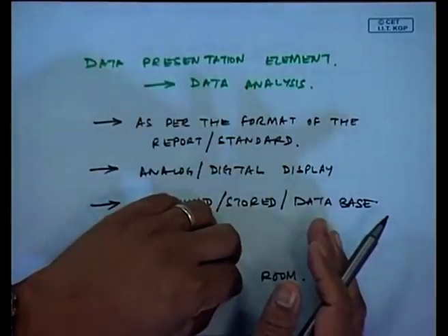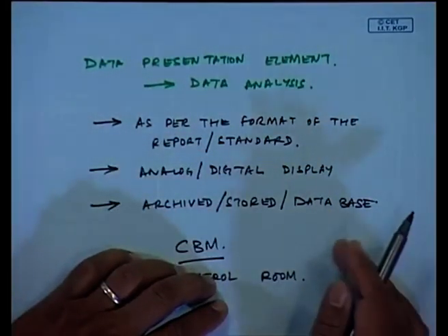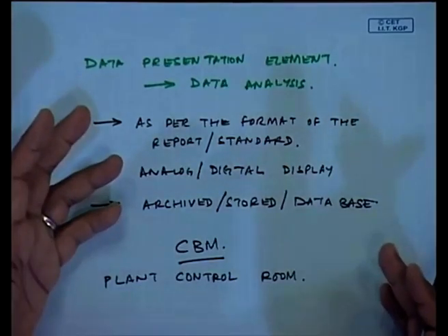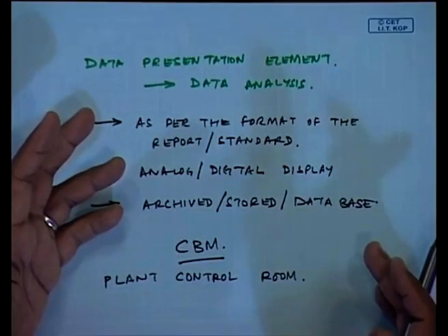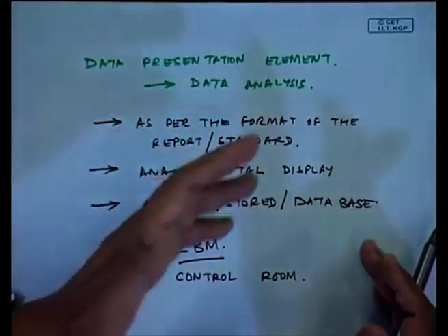Nowadays, you need not worry, it is totally manpower less, there is no manning. Everything from all the data transducers is put permanently around the instruments, signal analysis units are there, and data is being logged into a computer. If suddenly some data are abnormal, not as per the prediction models, you will get enough alarms. Alarms could be right there at the plant, alarms could be on your mobile phones also.